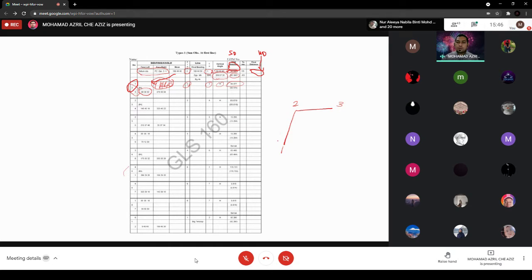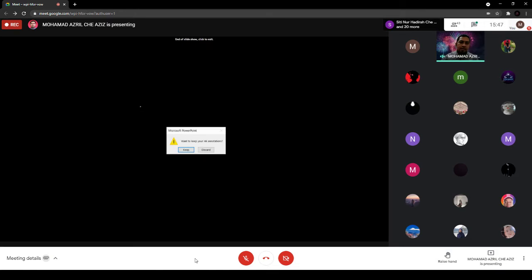Once you have set the value for 2 to 1, you loosen the clamp and then you target 2 to 3. You target 2 to 3, then you record the horizontal value here. In order to record this value, you need to check it against the previous value on the face left. The tolerance is within 20 seconds.